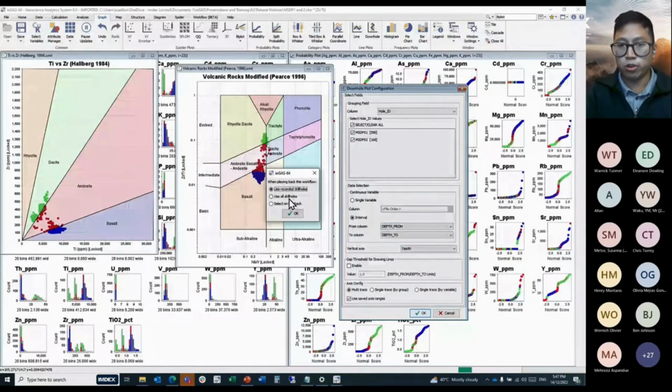But if I click on use all drill holes, it sort of simulates clicking on this checkbox. And the third option here, select on playback, will stop at this step and allow you to select the holes that you want to plot. But if you want to create a workflow that can run from start to finish on the new data set with minimal interruption, you will want to use the use all drill holes option.